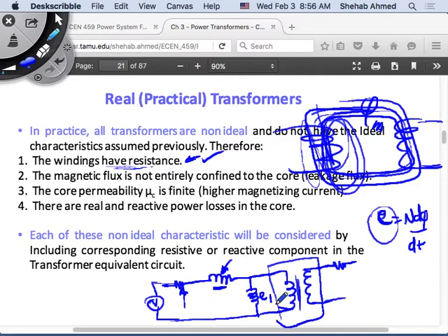After that, I'm losing some voltage drop because of the resistance of the windings, and it's burning power. So it's hindering me from producing my terminal power. It's something I need to subtract from my terminal power, so I need to put it in series. It's not equal to my terminal power, it's subtracting from it. Same thing with these windings: after you connect a load, current will flow in these windings as well.